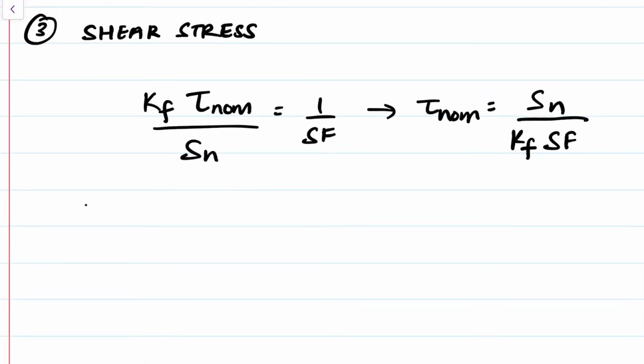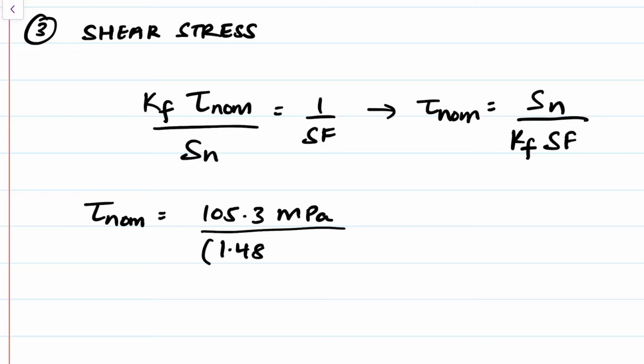So the stress I'm dealing with is equal to 105.3 megapascals divided by 1.48 unitless multiplied by a safety factor of 2. So my nominal stress in the bar or in the rod is 35.57 megapascals.